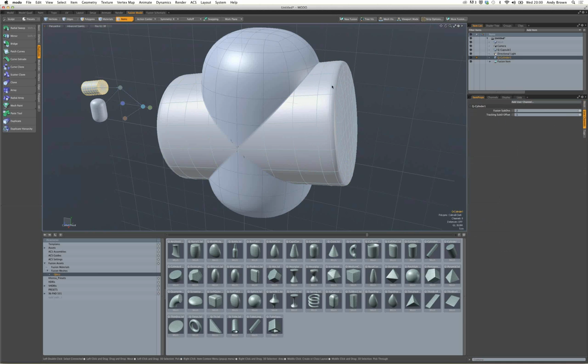When they started doing it, it wasn't working. The mesh was cracking. So it was just a question of upping these levels, subdividing some objects, and increasing the fusion subdiv level. As you pushed it, all of a sudden it worked, and the final result was amazing. So you do have to play around with those values. It won't just work first time when the object becomes more complicated.